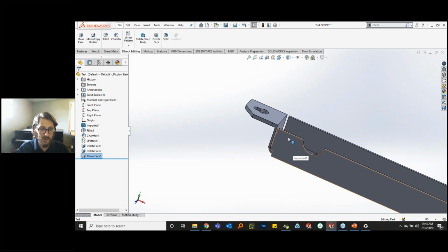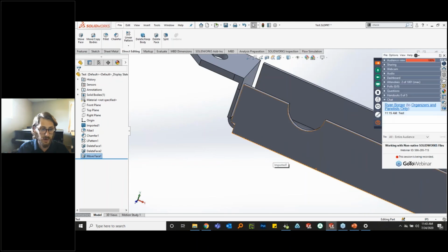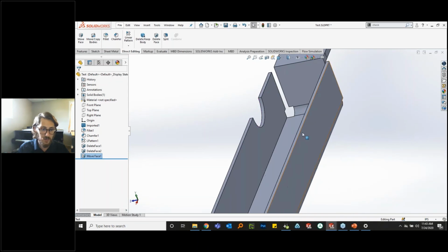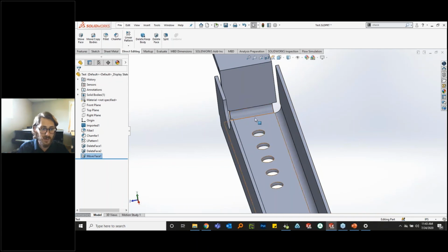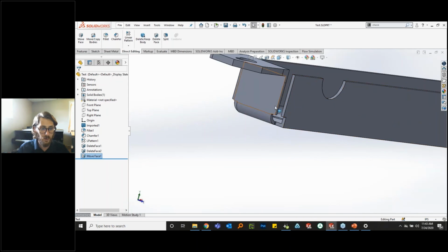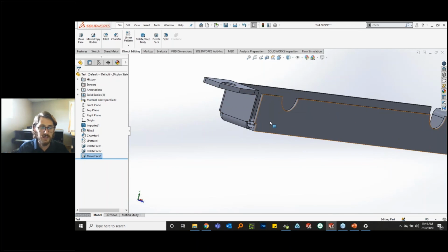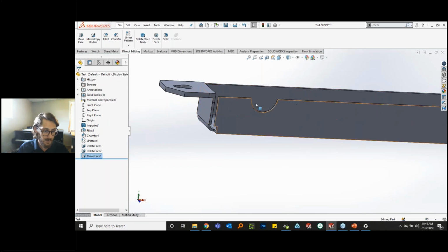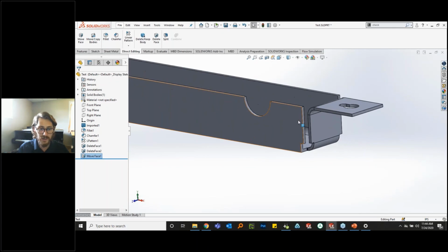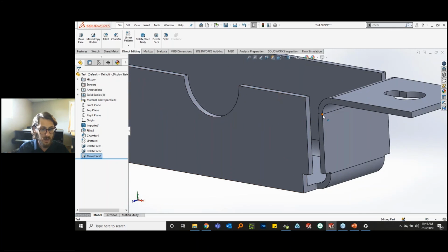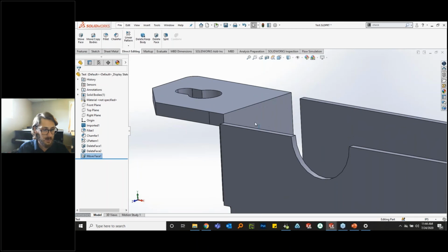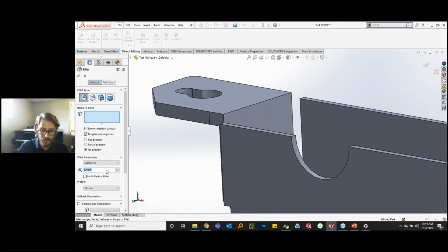Now, all I'd have to do at this point is repeat the process that we just exercised, where I am moving this face down here, removing any of these fillets, and we're effectively going to complete this by having all the faces translated to something slightly thicker. Now beyond that, let's say for instance, and to get it back to where it was previously, we've already verified that fillets work. So just pick the appropriate radius for your fillet.